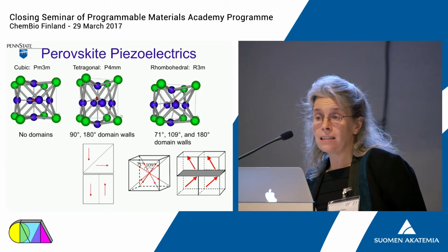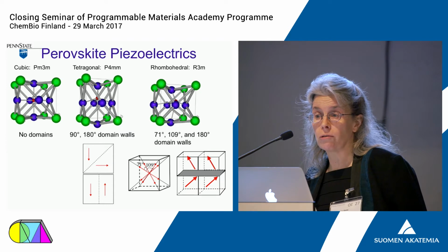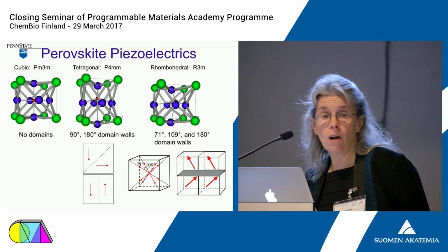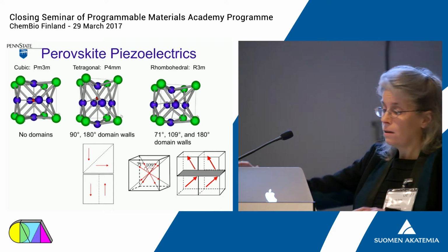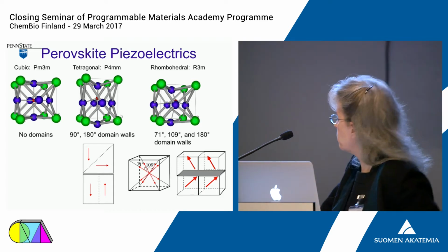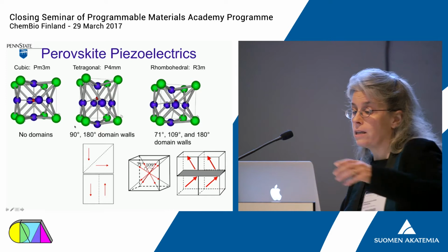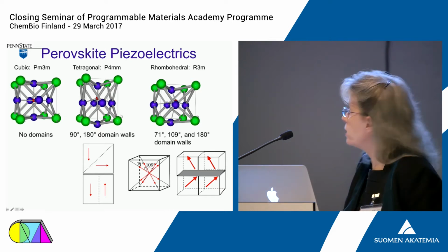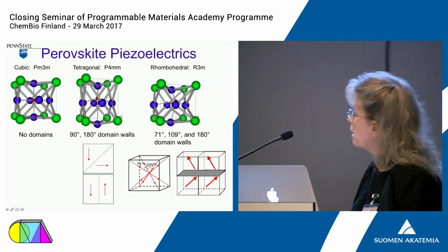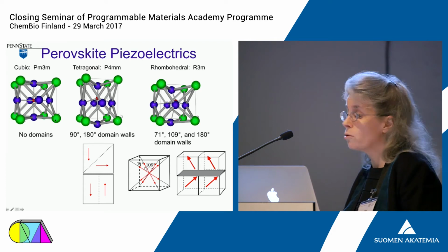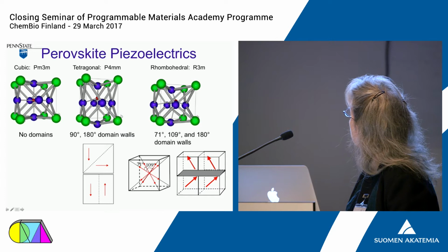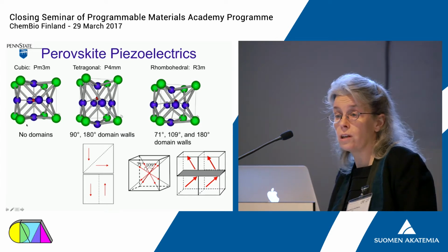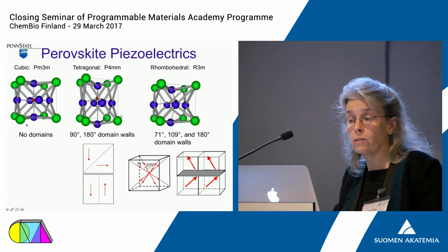So the very highest piezoelectric coefficients that are available in solid materials all appear in the perovskite crystal structure. And in the perovskite crystal structure, we have large ions like lead or barium that sit at the corners of a unit cell, a titanium or zirconium that sits close to the center of the unit cell, and oxygen atoms that sit at the centers of the faces of the unit cell.